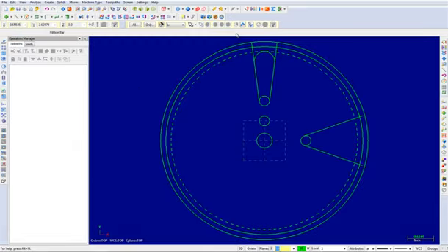In the next step, I will show you how to create an arc polar. Specifically, you will learn how to create an arc polar knowing the center point, radius, start angle, and end angle. Select Create Arc, Arc Polar.